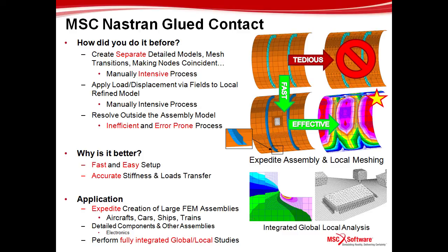Also, the value of glued contact comes into play when you perform glued contact with the basic Nastran solutions, Solution 101, and also Solution 103, 105, buckling, and all the dynamics. So here, the bottom right-hand side PC board chip is glued to the surface, so you can glue 2D and 3D structures together very efficiently, and then obviously you can perform dynamics. So glued contact is only established right at step 0 of any run, so that is now enabled in basic linear solutions as well.